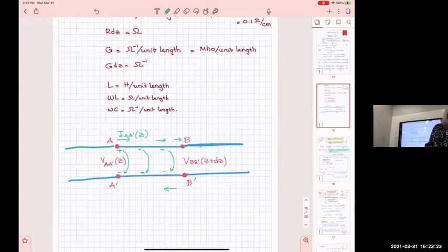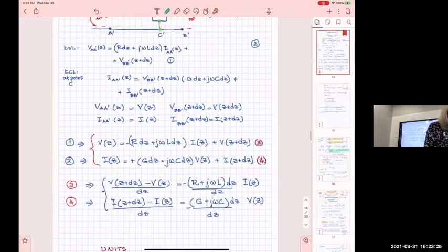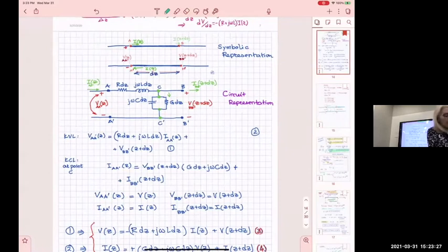All right, not like in circuits though, where we show only the current that goes through the elements of the circuit components, but we don't show anything that goes underneath in the other conductor, right? Unless we have other components, or we have to apply Kirchhoff's current law there. So in any case, I just wanted to remind you that the voltage applies between the two conductors, the current flows like this, and there is the return current flowing under, but we never show it.